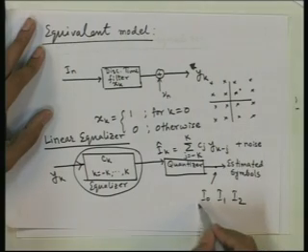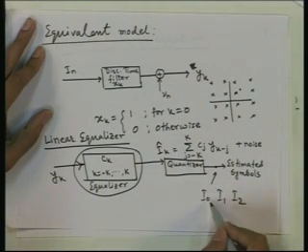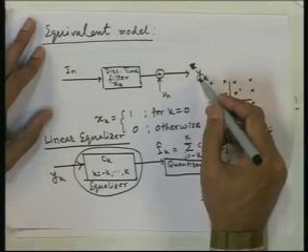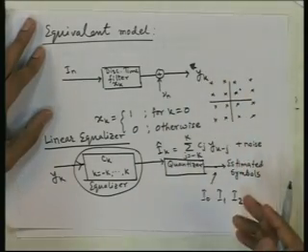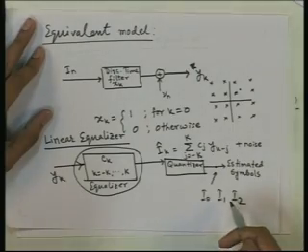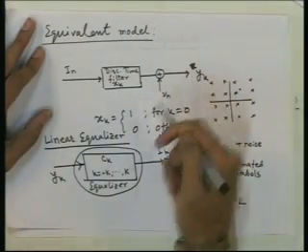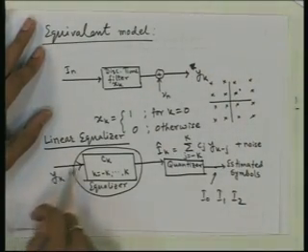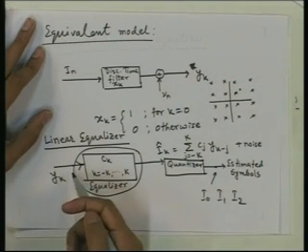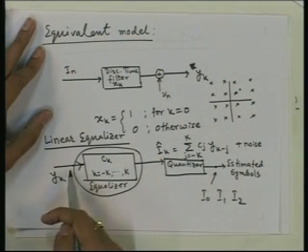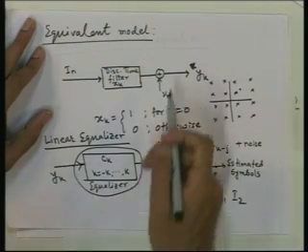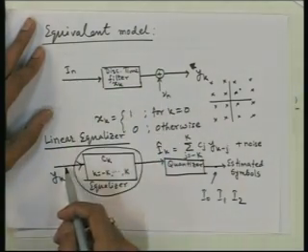So, we will be able to determine what is the contribution of I naught, I 1, I 2 on y k for the future symbols, and then we can cancel the effect of I naught, I 1, I 2 from the future values of the samples that we are passing to this equalizer, and as a result we will be getting a better estimate of these symbols, these I n's here itself.